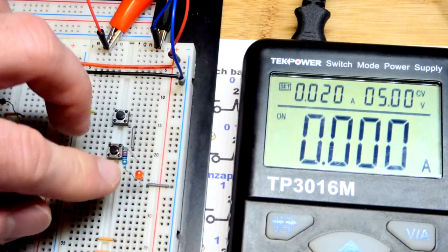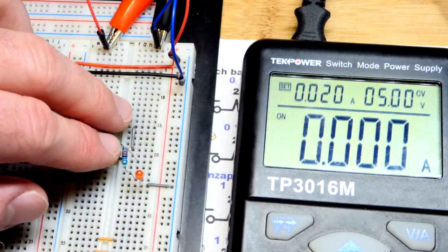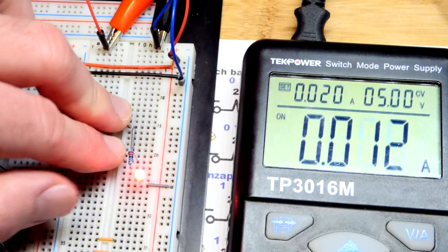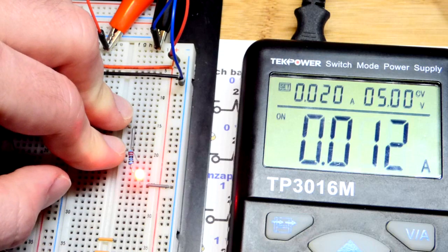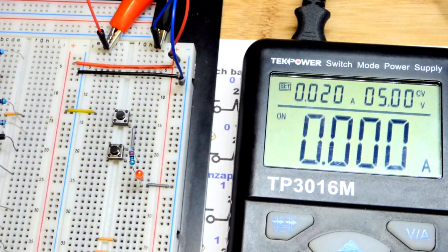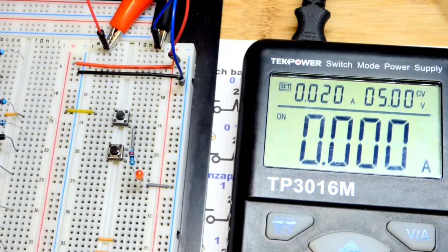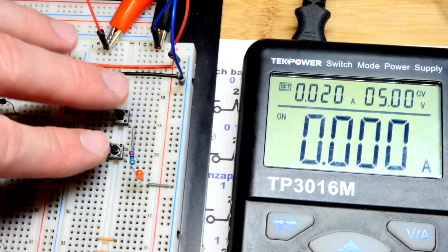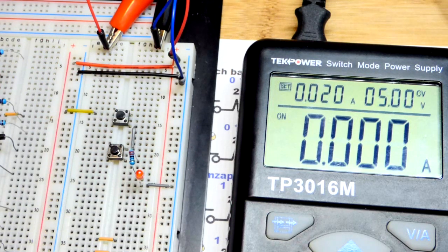So again, that's a 220 ohm resistor. The LED is dropping a little bit of the voltage there, but otherwise about 3.5 volts or so. It's going across the 220 ohm resistor, and it is setting the current. So current is limited enough to protect the LED and the resistor. So that's what an AND gate is. Again, I use integrated circuits for AND gates in most of my videos, but you can make them with a switch, and the switch one I think is easier to visualize what's going on.